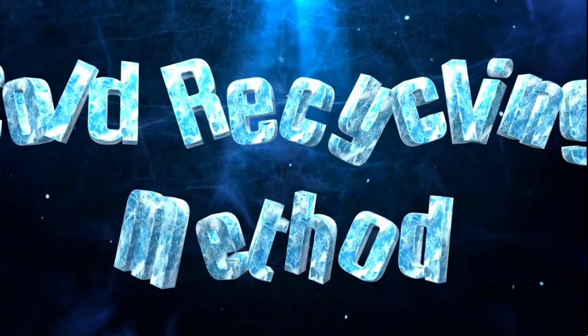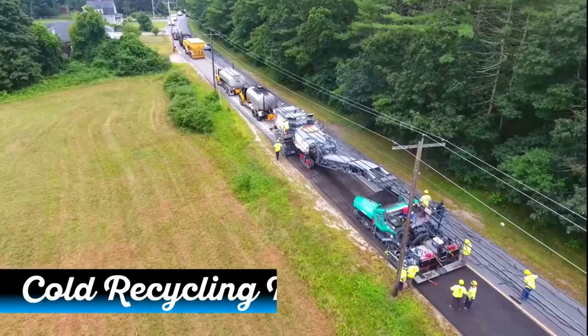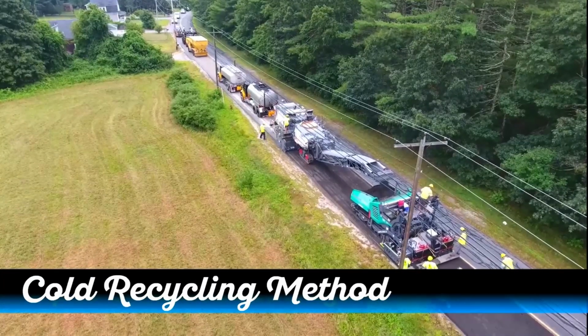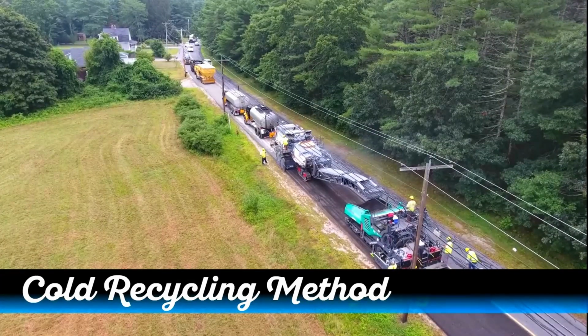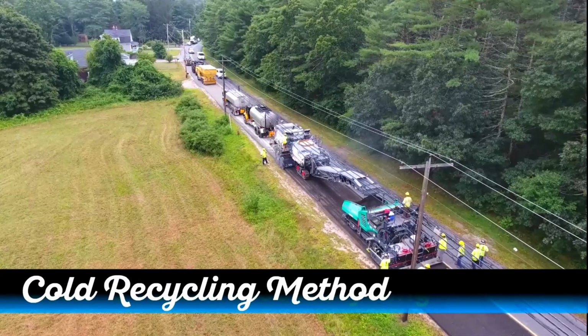Cold recycling method. What is cold recycling? Cold recycling is a road rehabilitation technique where the existing asphalt pavement is milled, crushed, mixed with binders, and relaid without heating the material. Cold recycling is performed at ambient temperature, making it eco-friendlier and more cost-effective.